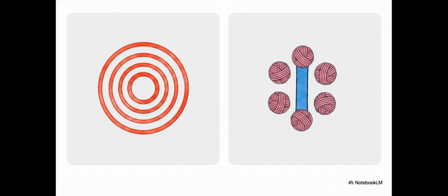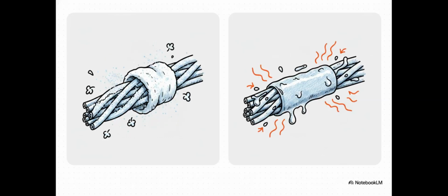High flex layers its conductors in simple concentric circles around a center point. It's really efficient for saving space, but those inner wires can crush under millions of automated cycles. Continuous flex, instead, uses this heavy-duty bundle-within-a-bundle design, twisting subgroups of wires around a central tensile strength member, something tough like Kevlar. Even the internal lubricants are completely different.